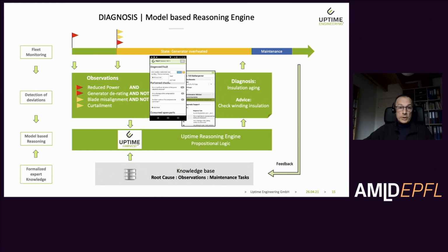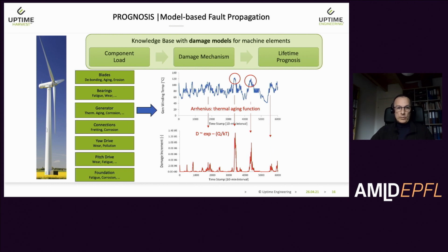And the question which remains is, how fast is that necessary? So how urgent is that activity? If we wanted to answer also this question, we have to refer to lifetime function modeling. With respect to thermal aging, the standard scientific approach is Arrhenius. The Arrhenius function links the aging kinetics to the temperature of that component.